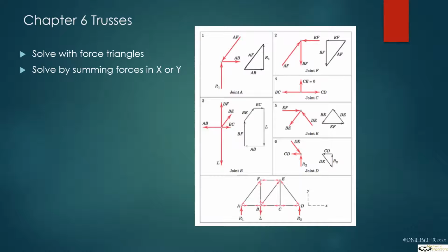In that situation, you can put them together like they show you as a triangle, and then you can just solve based on ratios. Generally, when you're doing trusses, we always start in a corner where we only have 2 unknowns, and then we work our way up through the truss. Because if we start farther up, then you will have more unknowns than we can do.